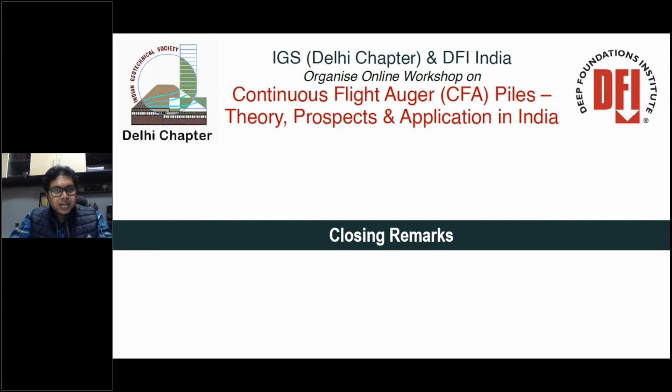Then there was the second presentation by Mr. Andres Keller from the UK. He talked about world case studies on CFA piles, from typical projects and extreme applications. He talked about the various processes and the applicable soils for CFA piles, discussed pros and cons, equipment used, different pile load testing, bidirectional testing systems, automated monitoring equipment, and he correlated the speed of installation with the soil profile. He talked about a few project summaries, the Avalon Hotel, a 20-story luxury hotel, Metro in Miami, and also some projects in Australia. So that was a very wonderful presentation by Mr.